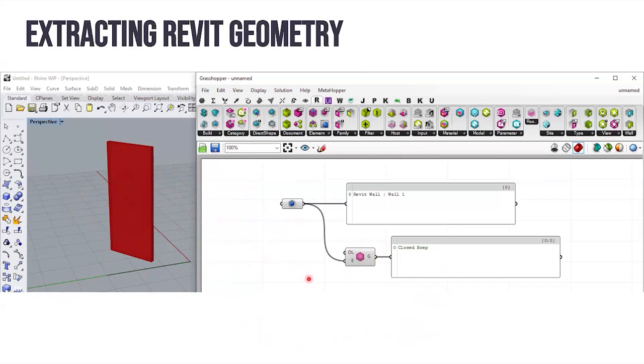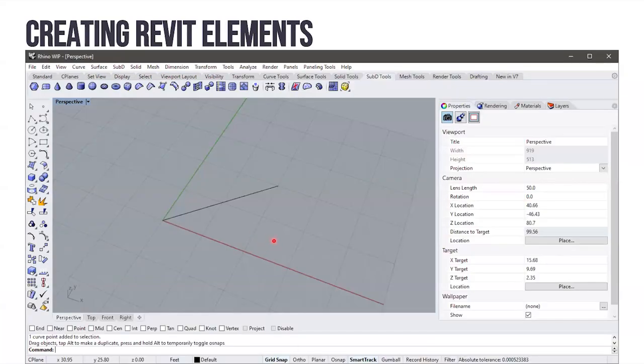The Revit specific Grasshopper components are one of the most important aspects of the Rhino inside Revit project. Grasshopper script components like Python and C# can also be used to access Rhino or Revit APIs simultaneously and create custom components in Grasshopper for your specific workflows. So we just saw an example of converting Revit geometry into Rhino using custom Revit components in Grasshopper. Grasshopper has many other Revit-specific components.